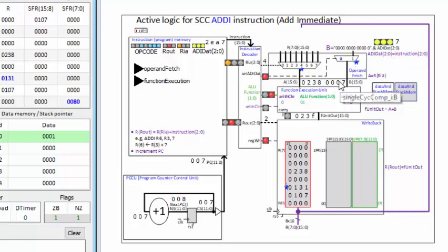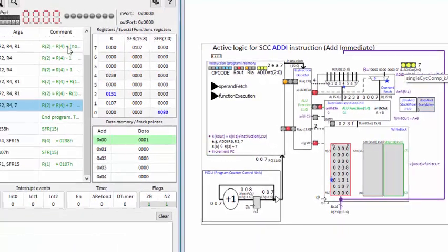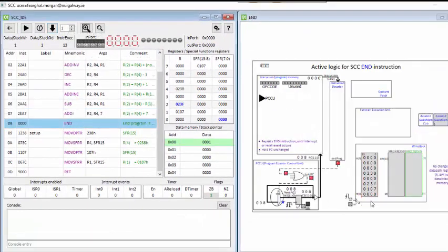You can see the value 7 is on B. And I add 238 to 007, gives me 23F. The RC in ALU function is the add as before. And the only difference now is that rather than A and selecting B as a register input, it's selecting B as the 3 bits of the instruction. And as I step, 23F is written to register 2. And that's the end of this program, and now it will hold the PC as other programs have done because end program is asserted in the instruction decoder.